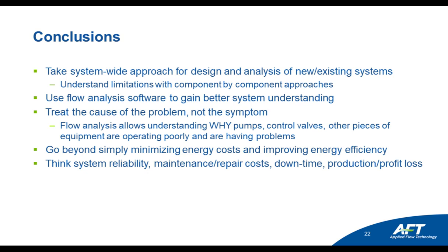And then you can also have a much better method of treating the actual cause of the problem itself, not the symptom. Again, quit just replacing your pump seals, or quit replacing valve after valve after valve. Use a flow analysis tool to help you understand why your pumps or control valves or other pieces of equipment are operating poorly and having problems.